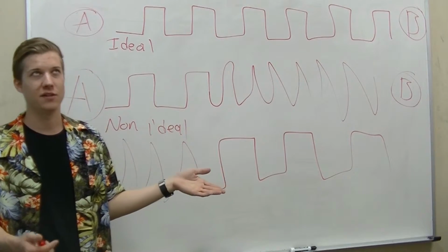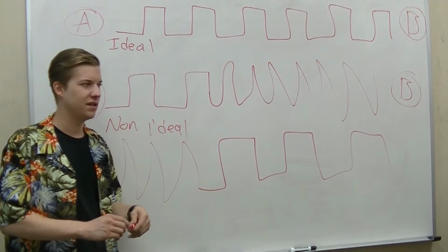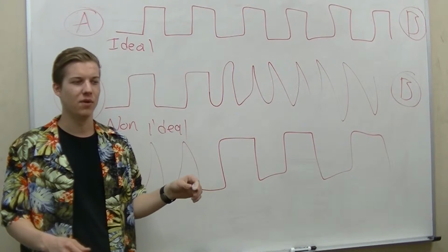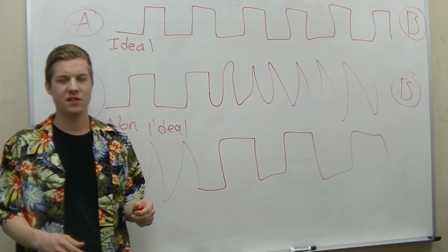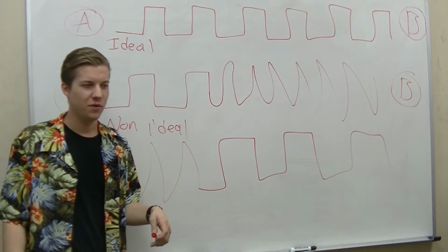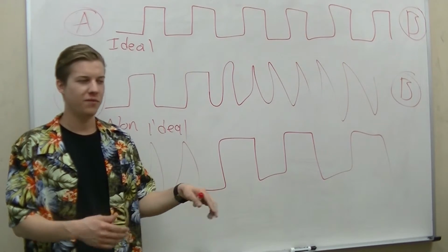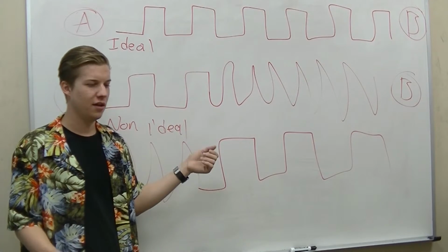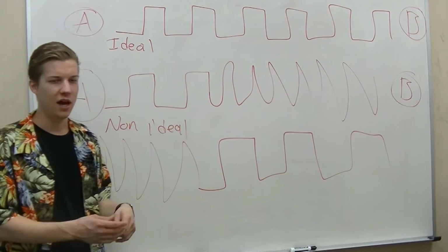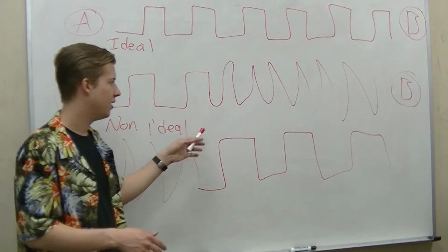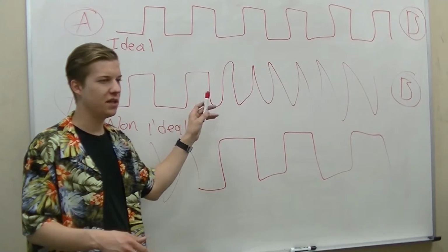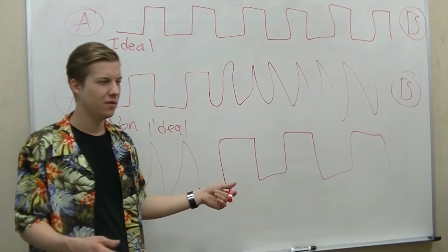And you see this system in a lot of devices, like if you buy an active HDMI cable or some sort of system that lets you use a USB printer over a long distance. Like things that normally you can't go more than a couple feet with. You'll generally see they'll add active devices to compensate for the parasitic elements of a wire.